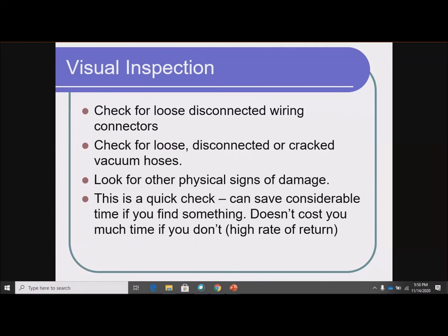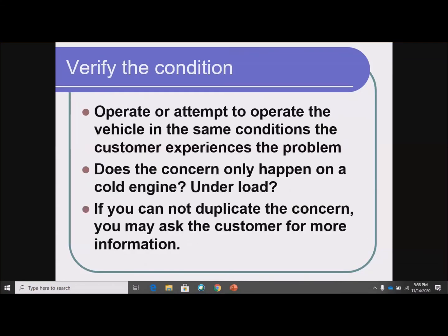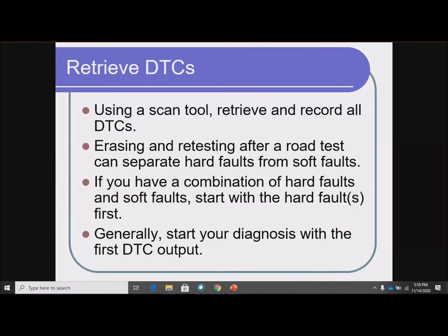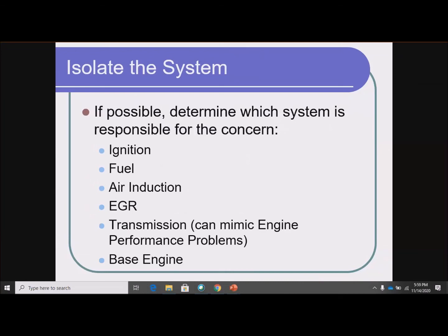Okay, so now you've verified the condition, you know the problem you're trying to fix. You know whether it exists right now or whether it happens only sometimes. You know what conditions maybe it happens under. This is where freeze frame can help you too, because freeze frame tells you engine RPM, temperature, engine load, things like that, the conditions that were occurring when the code was set. So you've got your diagnostic trouble codes. They should point you in a general direction for what system we've got here, right? If the car's not running right, I said this before, it's not doing one of those things right. It's not taking in an air fuel mixture, or it's not...